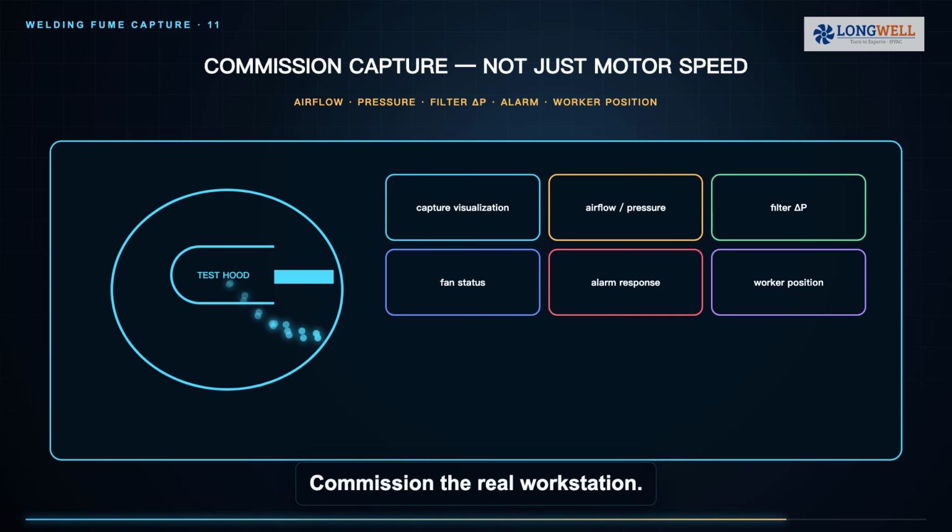Commission the real workstation. Use appropriate capture visualization, airflow and pressure measurements, filter differential pressure, fan status and alarm response. Check worker position, hood usability, discharge and clean makeup air. Repeat after process changes and on a planned maintenance schedule.